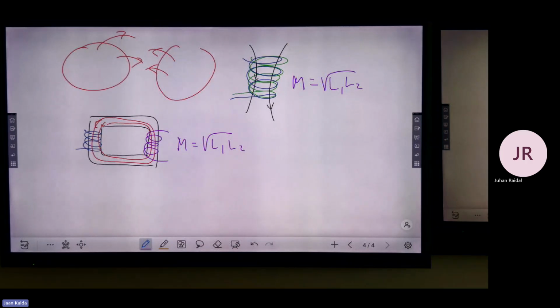What is that? 230 volts, and that is very dangerous, particularly if you have bare skin and are grounded well. It becomes dangerous when the current that goes through is larger than 30 milliamperes.